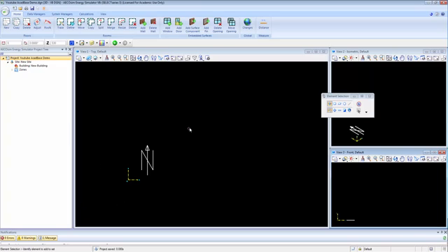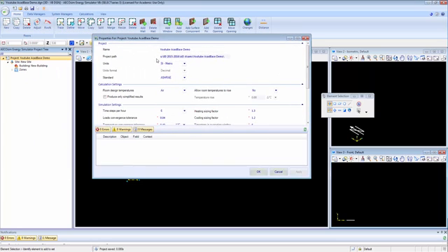Okay, now it's a good idea to start setting up all of the defaults first of all. So if I right click on this and pull up the properties, the name, the project path, units are going to be metric. That's good. Now standard here, you can use CIBSE or ASHRAE, so it's going to stick with ASHRAE for the moment. Room design temperatures are in here, so we're going to use airs, allow room temperature to rise, yes or no. I might as well just throw that on yes.